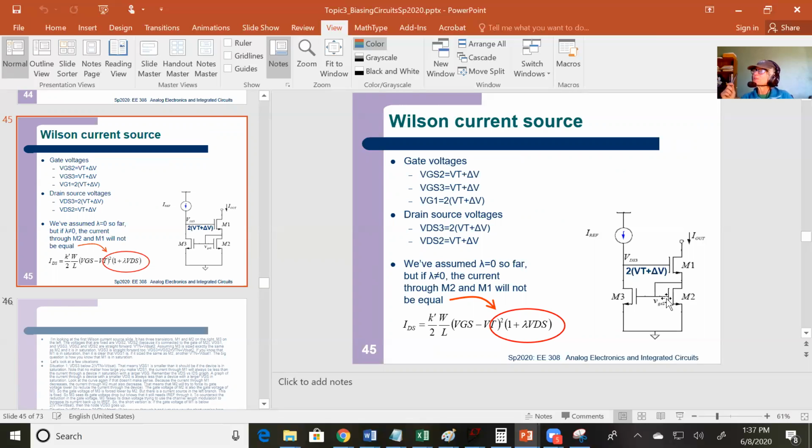Is it though? So what does a big R out mean? When you change the voltage across a big resistor, does the current change a lot or a little? Oh, just kidding. It's actually really good. Yes. So anytime you can up the resistance, then it's a big deal. So Wilson realized that and said, well, cascading is too hard. And cascading is actually better than the Wilson current source. So I'm not quite sure why Wilson gets all this attention.